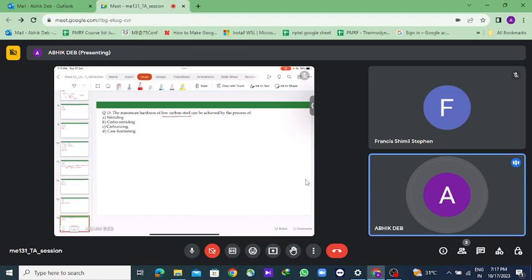For all these three processes, we can say we can use a low carbon steel. Yeah, low carbon steel, aluminum alloys also you can use. And particularly even medium carbon steels also you can use if you are only trying to harden the surface, as these are surface treatment processes, right? Nitriding, carbonitriding and carburizing, all of these are surface treatment processes.